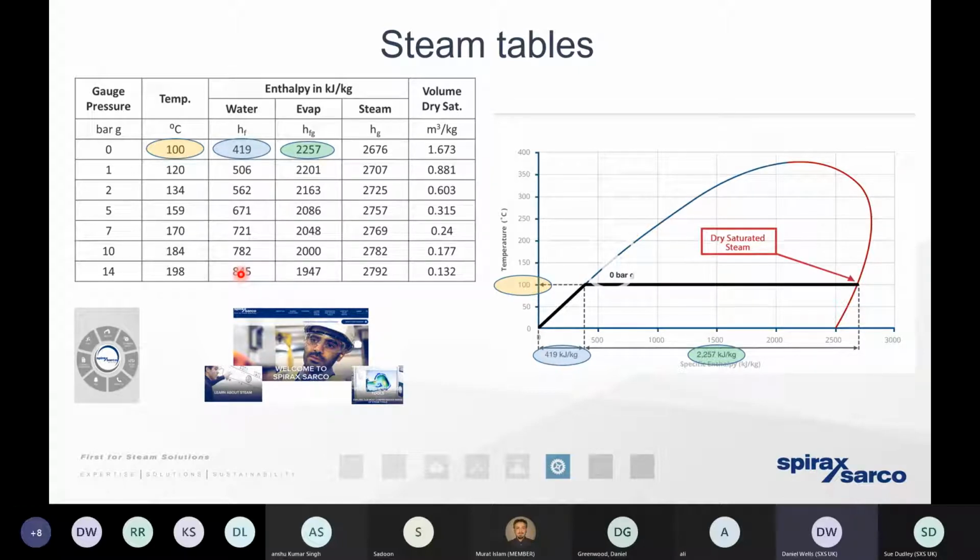There is a value to it. But there's significantly less energy in that hot water than there is in the steam. That's why we need to get it away, because if we don't do so, we're slowing down the rate of heat exchange. So when the steam condenses, it changes state, gas to a liquid. The enthalpy of evaporation, or the latent heat, leaves the steam and enters the process. The sensible heat is held back in the condensate.